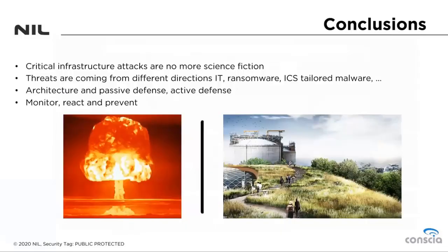Let's wrap up the webinar. We saw that critical infrastructure attacks are becoming a reality. Whether it is IT malware or ICS-tailored malware, industrial control systems and OT environments have experienced and will also experience attacks from different directions. Due to the tendency to interconnect IT and OT environments and also other issues we talked about, now it's the right time to address security. We should address security in the right order, which is first architecture and passive defense, then active defense.